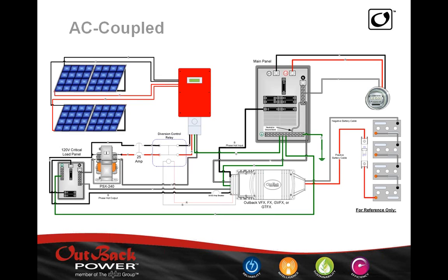And so a lot of people realize that even though they have a PV array and an inverter, because the inverter is programmed to follow the UL 1741 windows and the IEEE 1547 guidelines, they stop injecting energy. So essentially they are without backup just like everybody else. And so a way to add backup to a system that didn't have batteries is to couple a battery-less inverter with a battery-based inverter on the AC side. So this AC coupling system allows an existing system to have backup when the grid goes out.